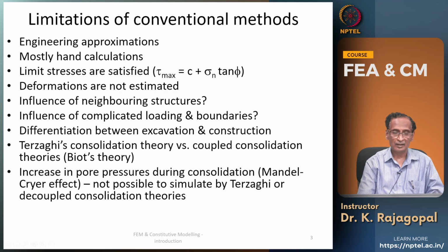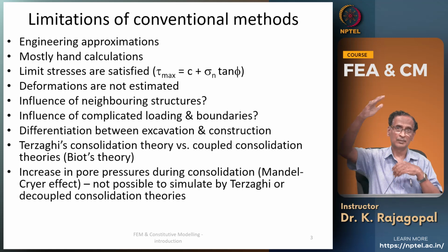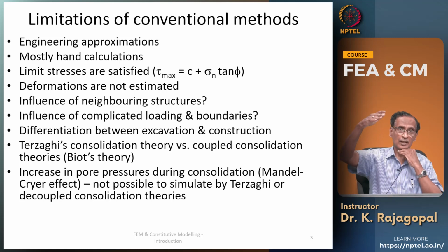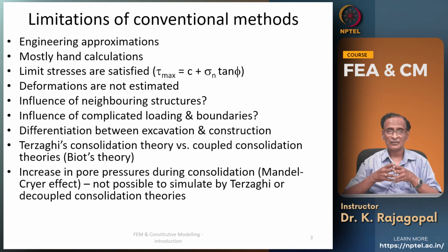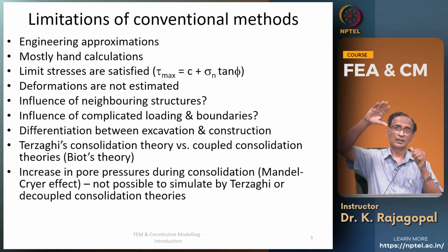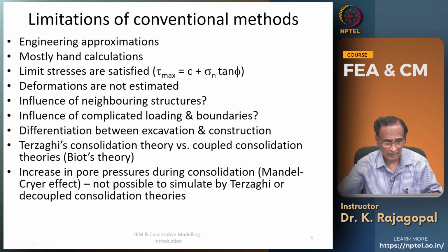And the one feature that we will not be able to replicate by using Terzaghi's theory is the increase in the pore pressures. In Terzaghi's theory, it is assumed that the pore pressure is maximum at the initial construction time, and then gradually the pore pressures will go on decreasing with time. But if we look at more rigorous models like Biot's theory, sometimes the pore pressures might increase with time initially and then start decreasing, and that is called the Mandel-Cryer effect.